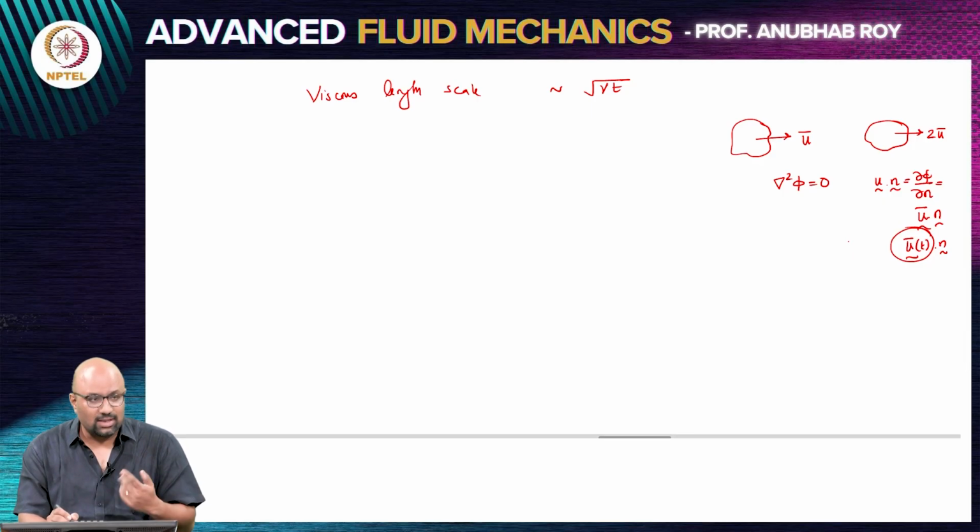But the potential that we solved, for any problem, for any configuration, is only dependent on the instantaneous velocity of the object. You do a change, and the velocity field that you obtain will be exactly related to the velocity at that point in time. The potential doesn't care what the velocity was at an earlier instant of time.